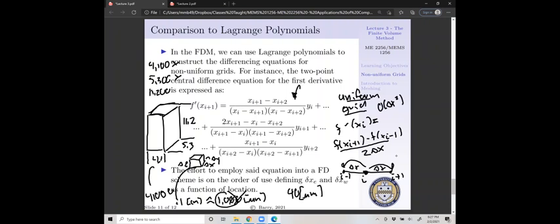if we did a 10 micron mesh just for this one thing that has these really, really tiny dimensions, you're talking about, I'm taking this to Wolfram Alpha because that's way too many numbers for me to count off the top of my head. That is 2.4 times 10 to the 11th, 250 billion elements. So sometimes this gets out of scale really, really quickly.